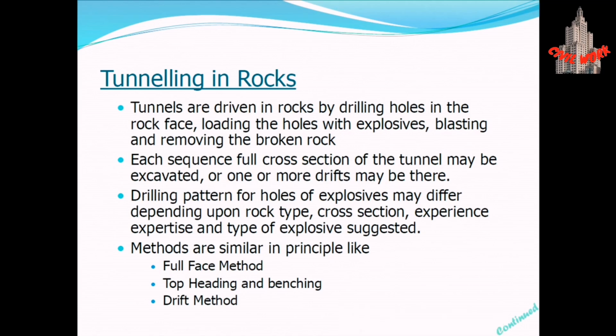In each sequence, the full cross section of the tunnel may be excavated, or one or more drifts may be used. The drilling pattern for the explosive holes may differ depending upon rock type, whether metamorphic, igneous, which is the strongest rock, or sedimentary. The methods for tunneling in rocks are the full face method, the top heading and benching method, and the drift method.